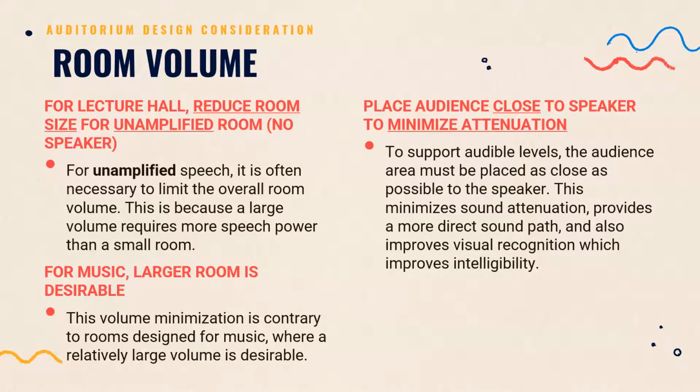Next is room volume. Does room volume affect acoustic experience? Of course, yes. For lecture hall, we need to reduce room size, especially for unamplified room, means room without speaker. Because bigger room means bigger power output. Okay, power in terms of both speaker, both electric and our voice. So if we didn't use mic and speaker, means we have to speak louder.